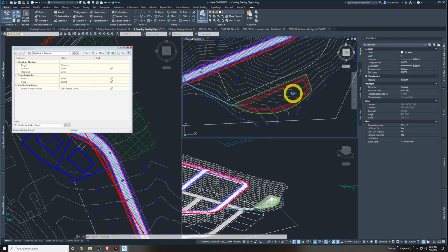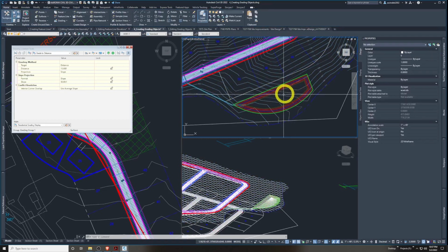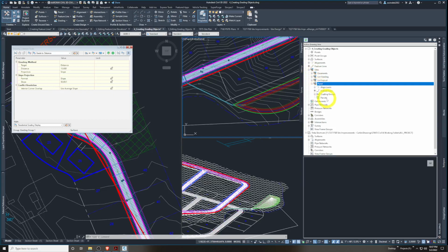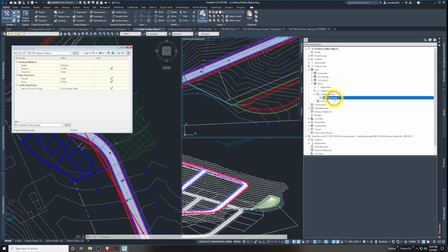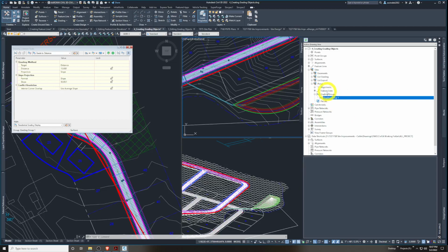Give it a minute while it thinks. And now that I'm out of the infill command, that's been created. And remember, in tool space, these are being populated under here. We put them in this site. The grading groups are being created under here. Here they are. There's 2 of them created. One was an infill, one wasn't. All right.